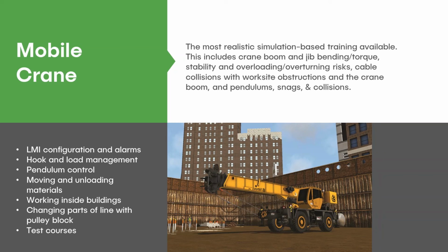If you want to, with all the cranes, you can make it so the next load sticks to the ground through the instructor station. When they attach and they try to lift it up with their slings and it doesn't move and they get the overload alarm, watch what they do. Do they put it back down and put their hand up and say something's wrong? Perfect. Do they struggle and strain? Then they need to learn more respect for the machine. So all that's inside all the crane operations.